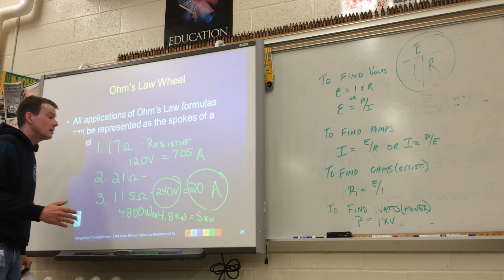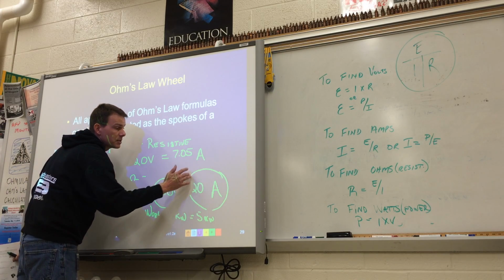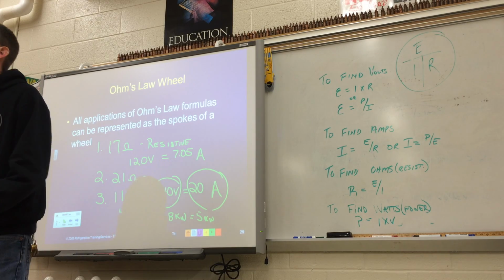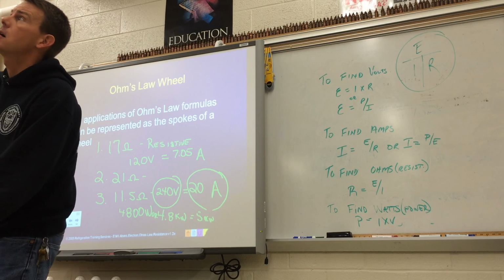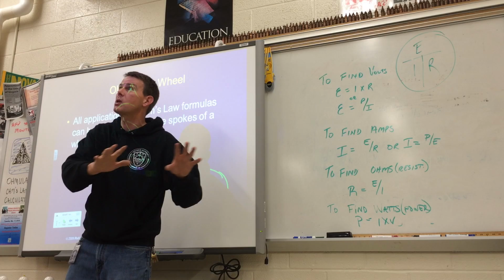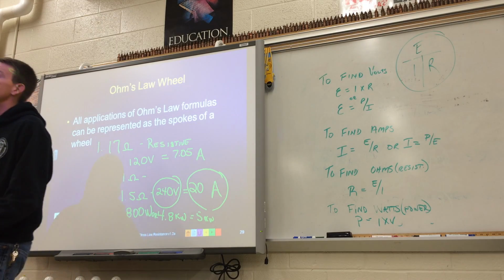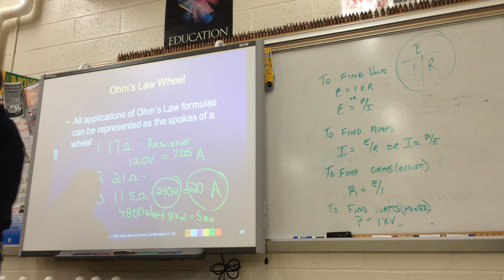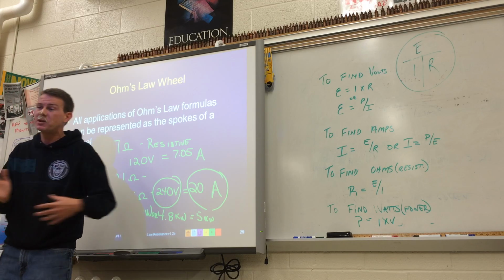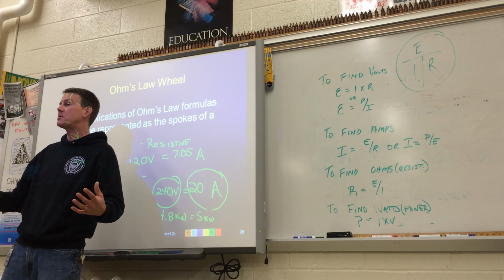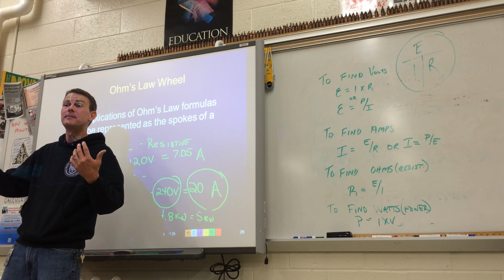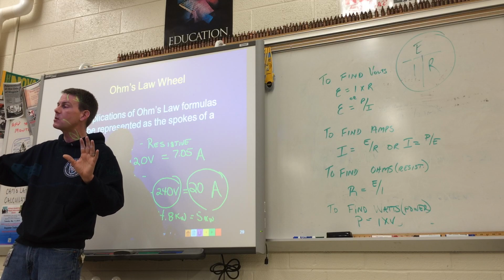So the ones that run through the kitchen in your house, what do you have plugged in your kitchen? Refrigerator. That's going to draw a lot of power, more than a light. Oven. All right, the oven's on its own separate 240 circuit if it's electric. If it's gas, it's something different. Microwave, yes, that's got to be on its own circuit too. Because if the microwave pulls 10 amps and the refrigerator pulls 10 amps, that's 20 amps right there. It's going to trip the breaker every time you try to run both at the same time. So they each have to be on their own circuit.